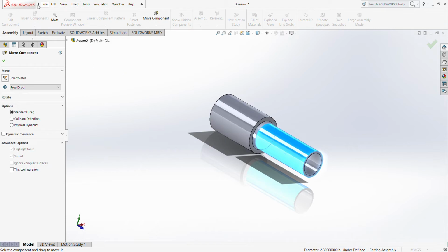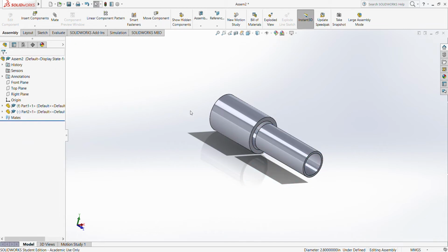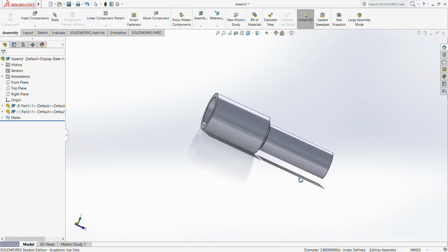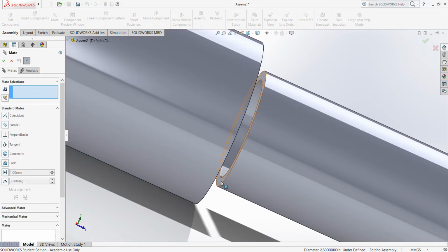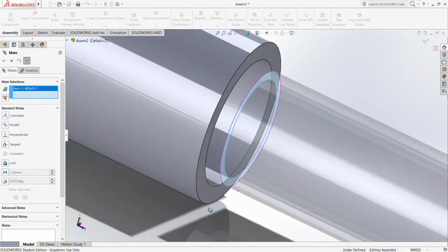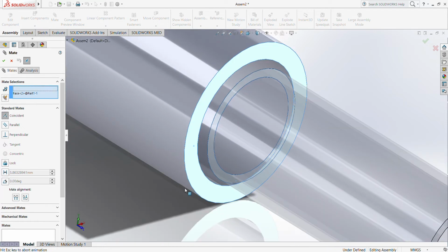So you go to the SolidWorks menu bar, go to File. Wow, I have to hit escape there. Go to File. Well, I showed you right there. So right now we're inside the. Let me escape out of this. We're going to go ahead and just weld these two pieces together. So to do that, I'm going to pan the object. I'm going to hit Mate. Now I got to select two surfaces. I'm going to select the surface of the smaller cylinder, and this one of the larger.